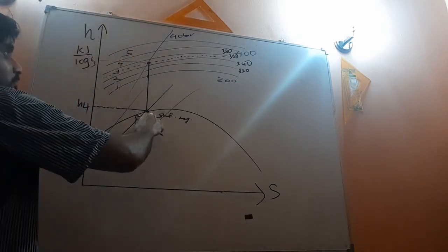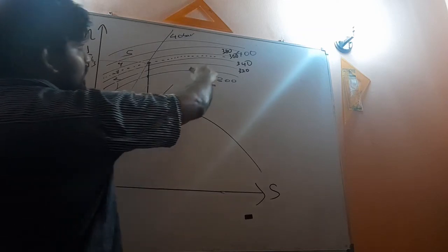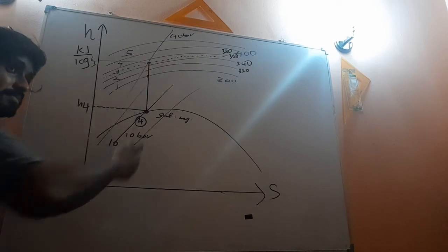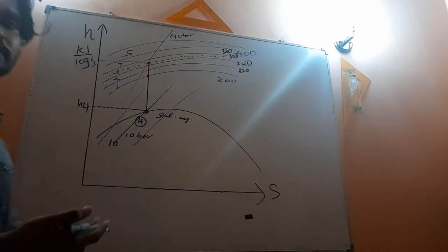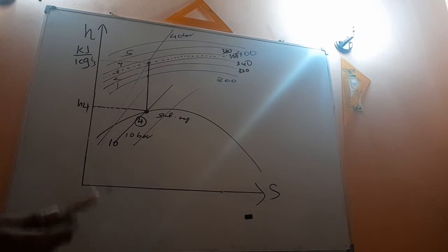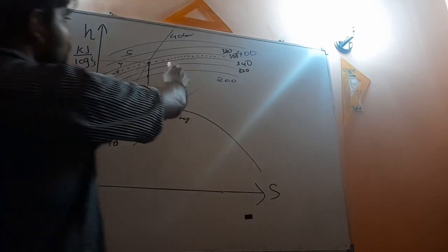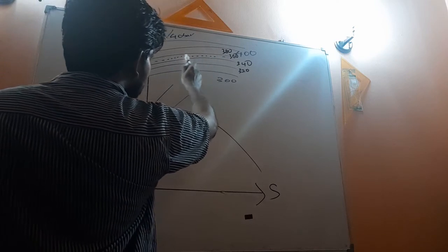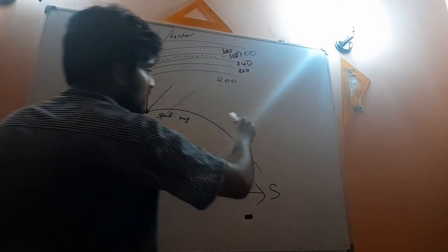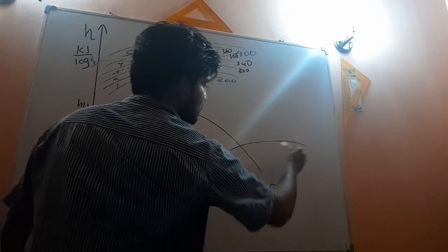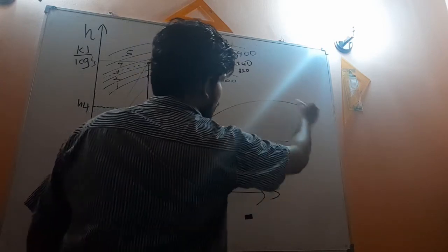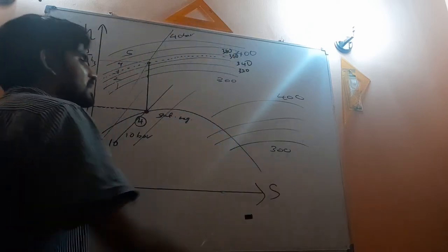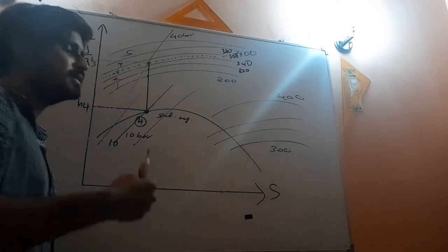From this point onwards, it is again heated until 350 degrees Celsius, at the same pressure as at the end of the first stage expansion, which is 10 bar. So again, you have to consider this imaginary 350 degrees Celsius line. The reason is that between 300 and 400 there are 5 subdivisions, where one subdivision has a range of 20.